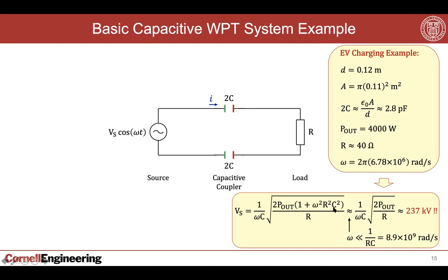And the reason we used this approximation for calculating the power is that the knee frequency that I just talked about is more like over 1 gigahertz. And so clearly when you're operating at 6.78 megahertz, there's no way you're going to get up to where the capacitor starts looking like a short circuit, right? Now, why can't I operate things at a gigahertz? Well, first of all, you have to generate this sinusoidal or square AC voltage, as only the AC current will go through the capacitor.